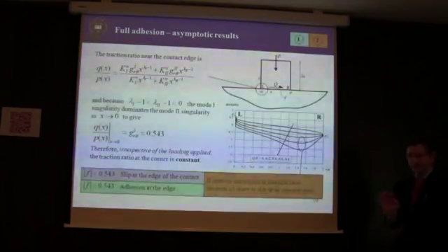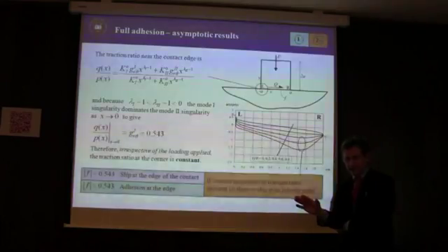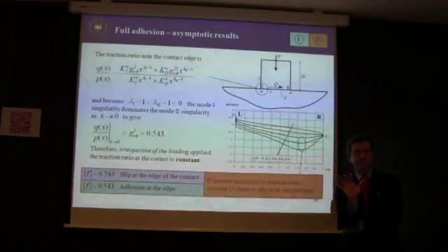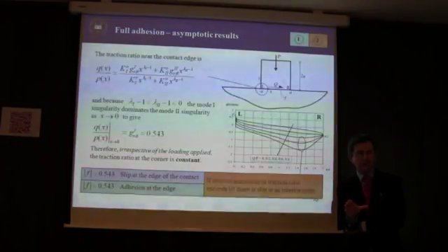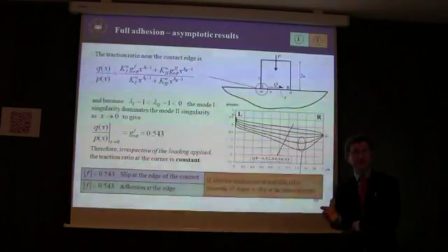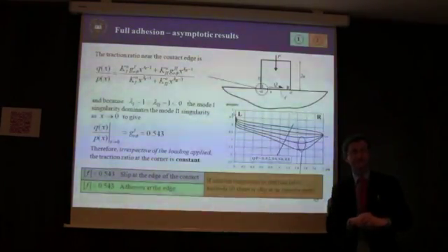So let me just stop there for a minute. So where we've got to then is to say that the Williams solution can tell us when a contact corner is emphatically turned into a notch, simply in terms of the friction needed to stick the corners together.